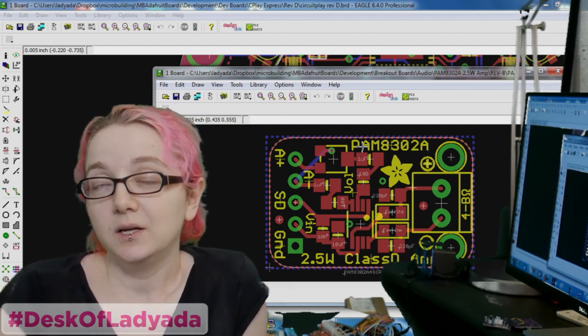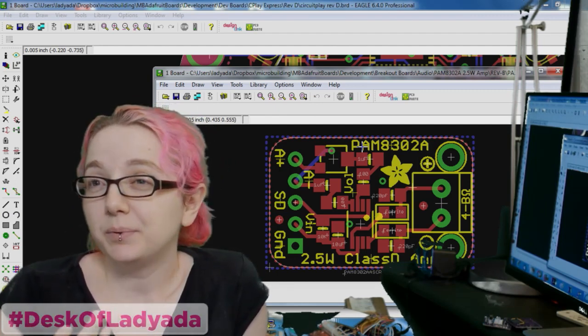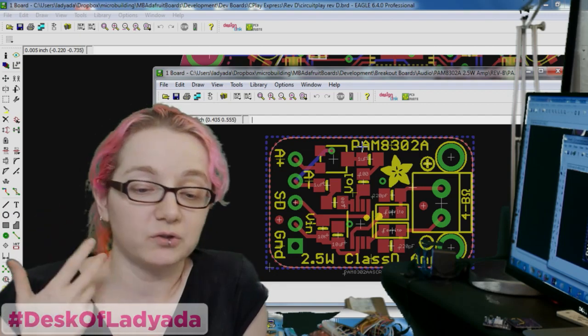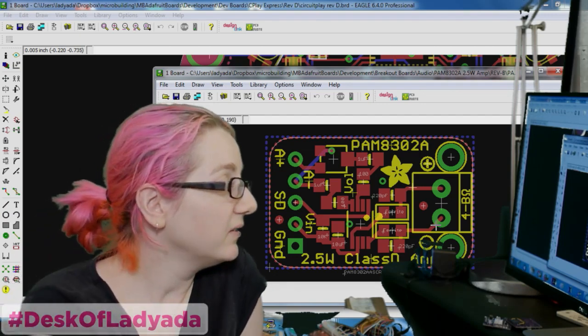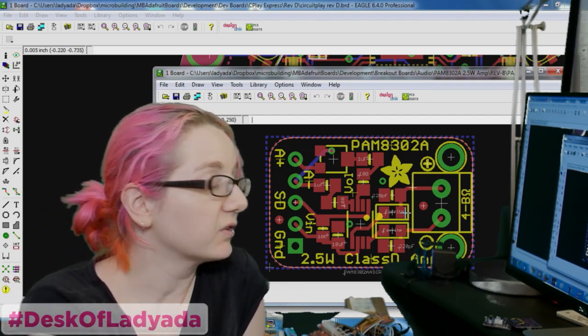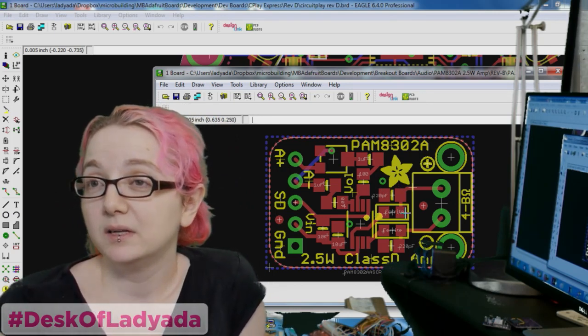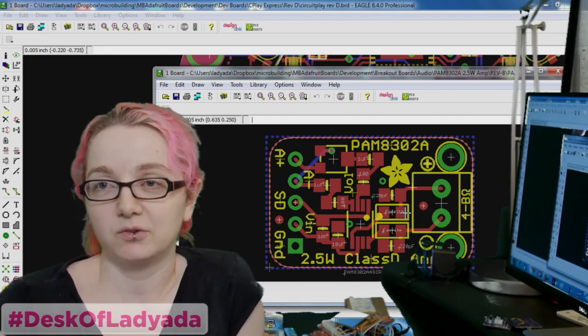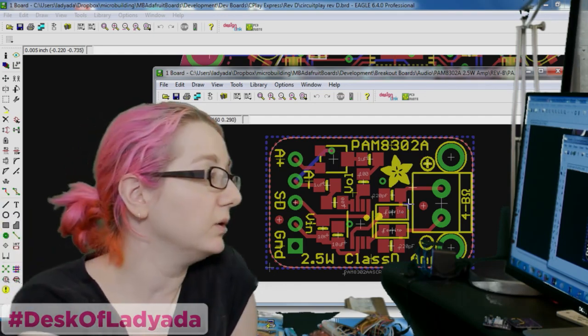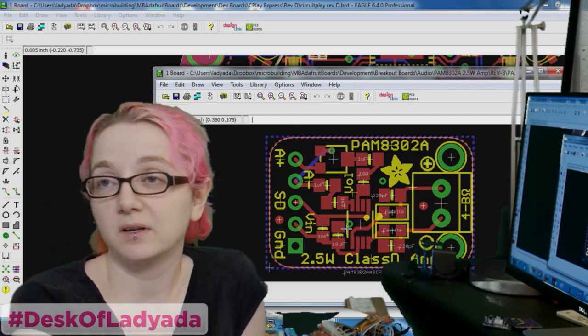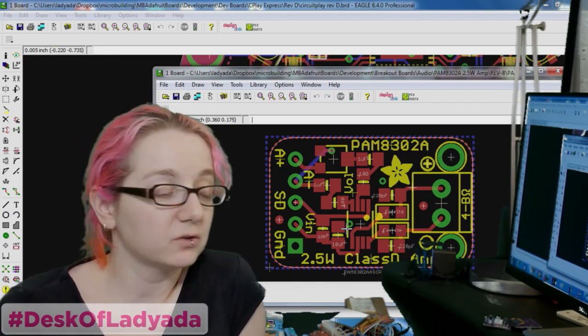They're not cheap. They're usually a little more expensive, because there's some logic inside of them. But the nice thing is that you don't need a lot of external circuitry, and they can be very small. Compare this to an LM386, which has big capacitors. You don't need a lot of big capacitors, and often there's gain control.